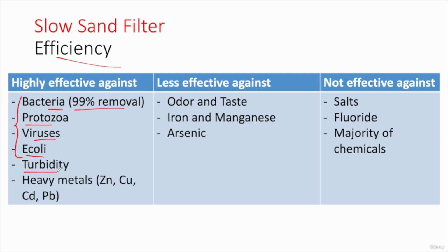Also highly effective against turbidity if our turbidity is low, as we have already said. And this is reduced through the physical filtration in the sand media, and also highly effective against heavy metals like zinc, copper, cadmium, and lead. Less effective against odor and tastes.